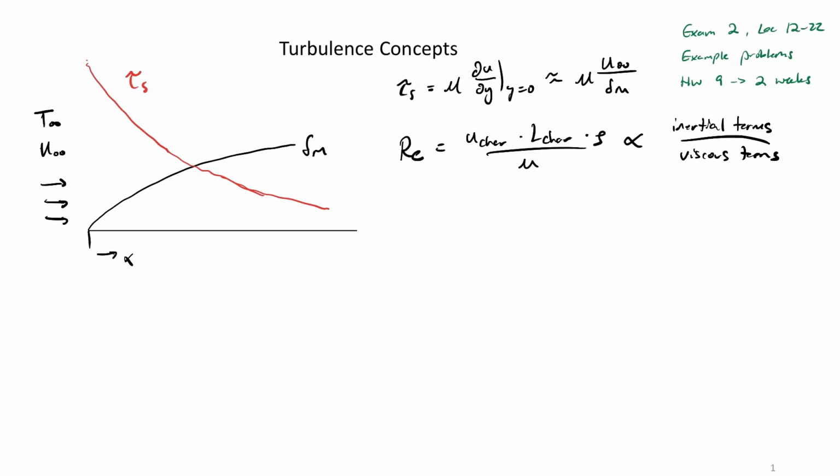that's my Reynolds number. So if we think about this, as we continue to go out in X, and that shear stress is changing, my viscous force is decreasing, the Reynolds number is going to eventually get to a point where the inertial part of the flow is really dominating over any kind of shear stress. And in that situation, the flow can become unstable, right? Any slight change in inertia is not suppressed by the viscous shear, and it just causes these eddies and disturbances in the flow to start forming.